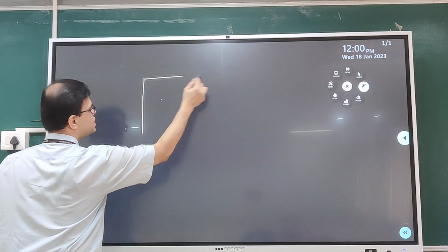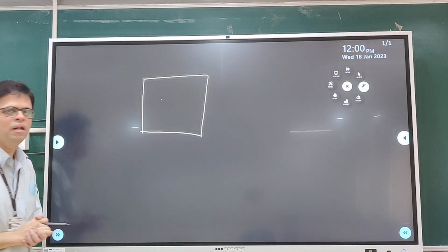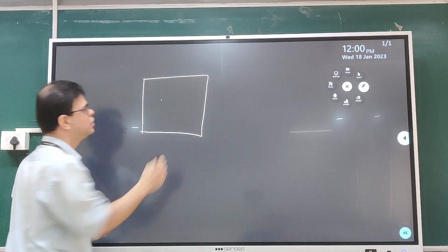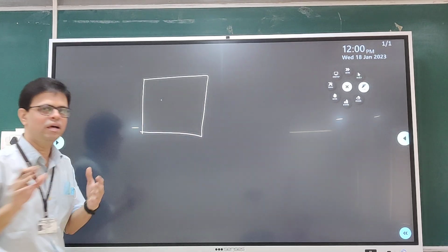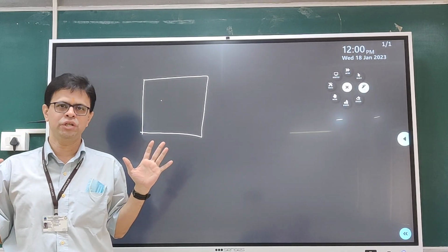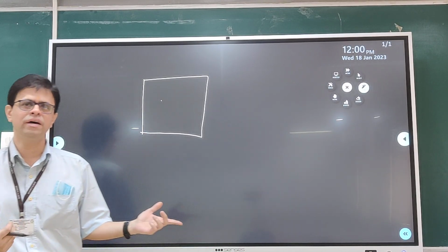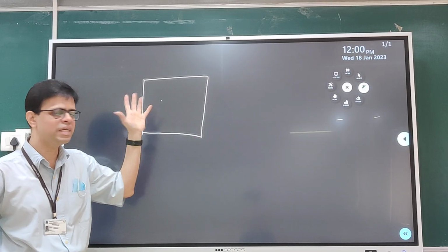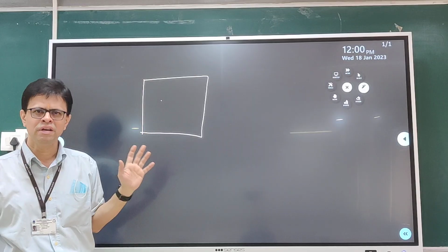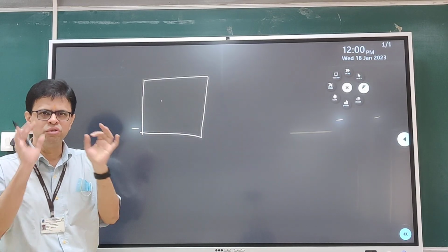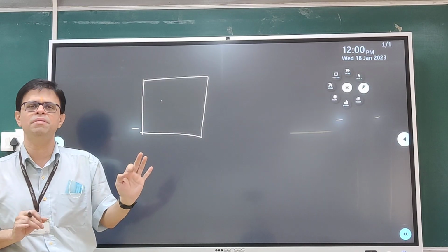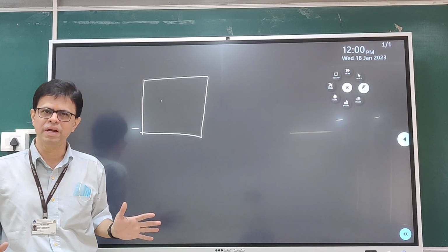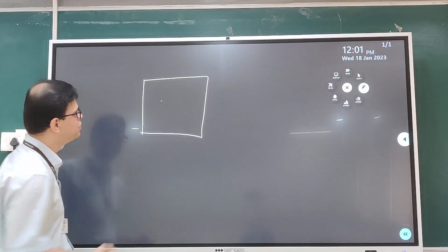Now I will start with a simple patch using a slot to realize circular polarized radiation. I have taken a rectangular patch. Of course, similar designs we will talk about later in circular patch as well as equilateral triangular patch. This is one of the best techniques because we are not using a dual feed or a power divider. Using a single patch with slight modifications in the patch geometry, using a slot and a single feed, we realize a CP antenna. Now how does it go?